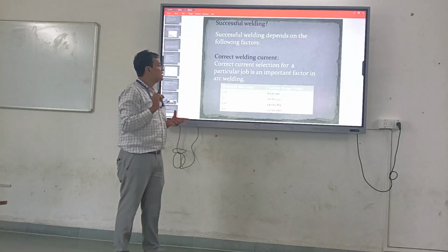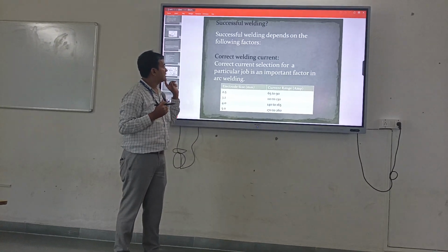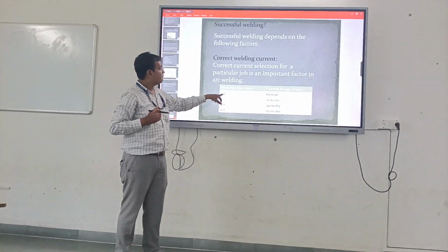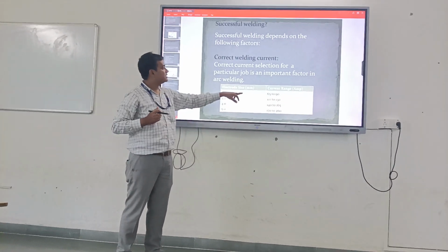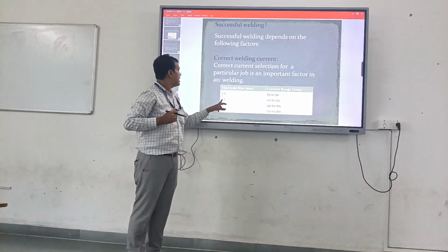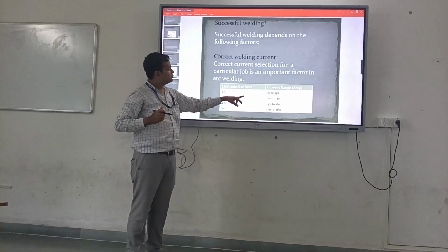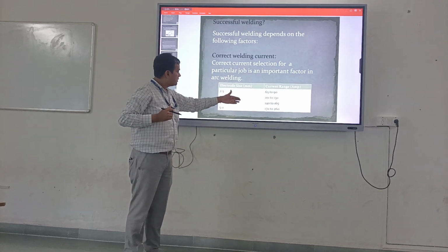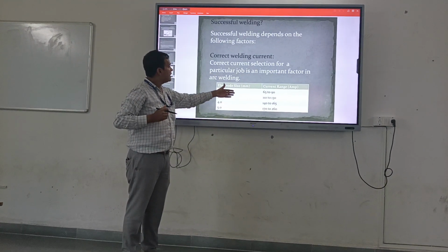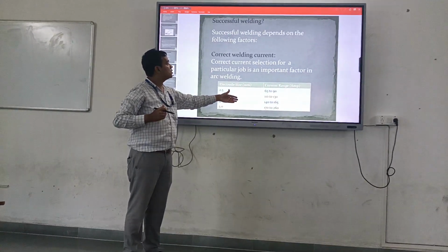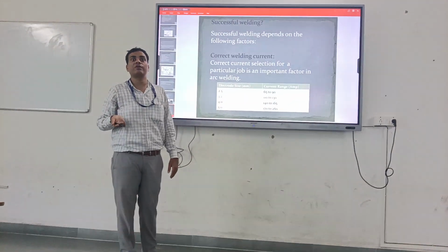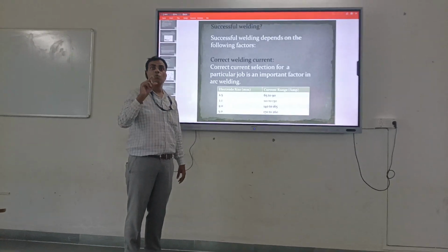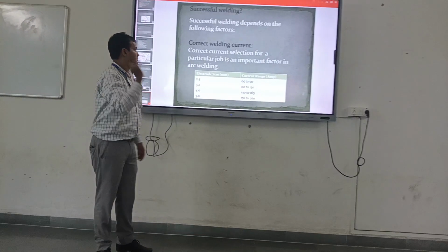Then I will decide the current range and electrode size. For a 2.5 electrode size, the current range is 65 to 90 ampere, and for 3.2, 110 to 130 ampere is required. All the data is given there according to the electrode size. The electrode size is also defined on the basis of the thickness of the workpiece or base metal.